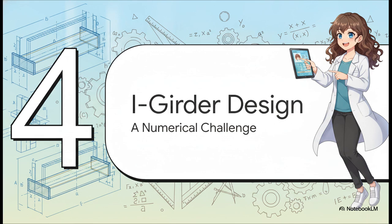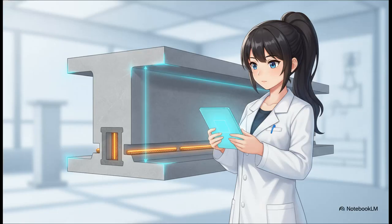Buckle up, because this is where our design gets very real. We're tasked with checking the ultimate strength of a massive I-girder for a bridge. It has an effective span of 24 meters, uses high-strength M50 concrete, and utilizes those bonded 7-wire strands we were just talking about. The top flange is 600 millimeters wide and 150 millimeters thick.